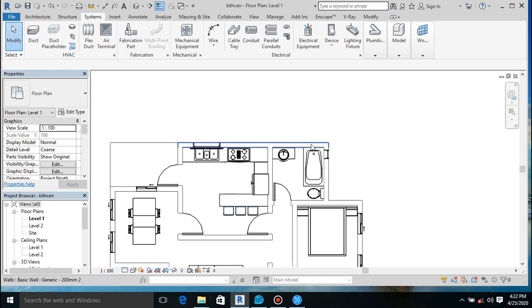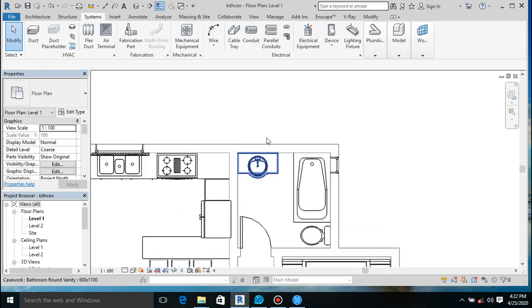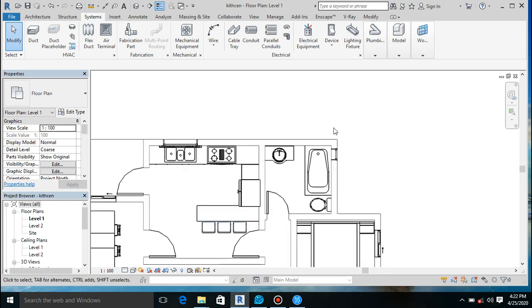You need to keep something in mind, which is you have to have a stationary base pipe. What do I mean? A pipe that you will relate the other pipes to, which is if it is at a certain level, all the other pipes will come to that level to connect to it.